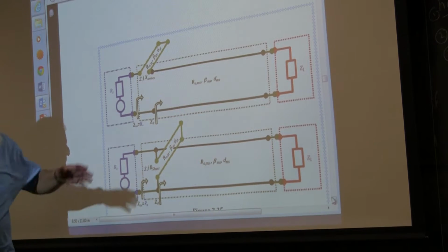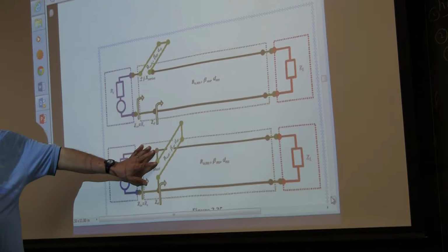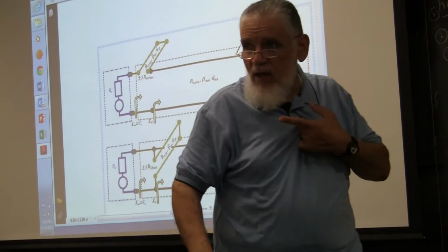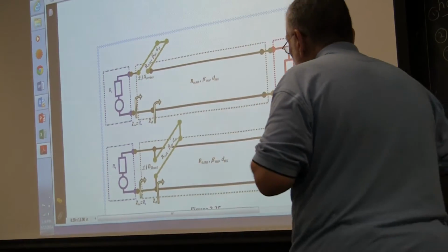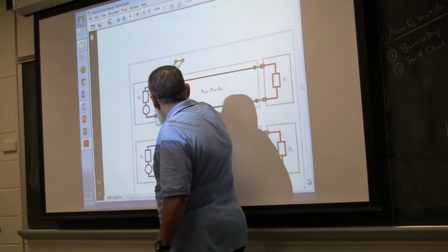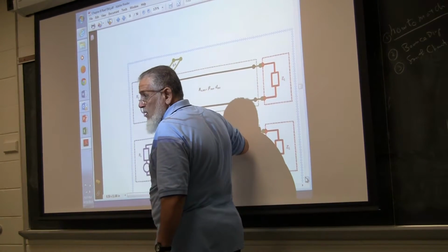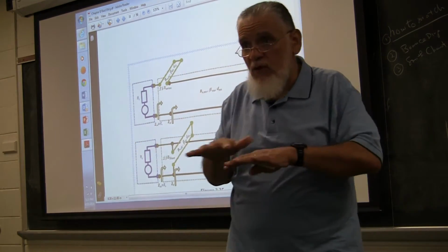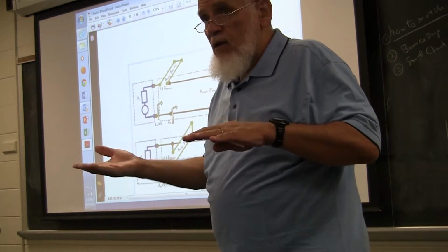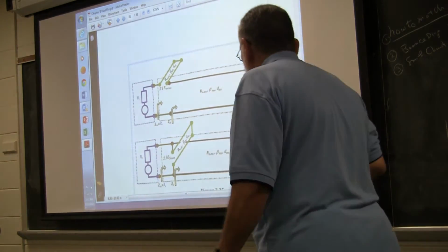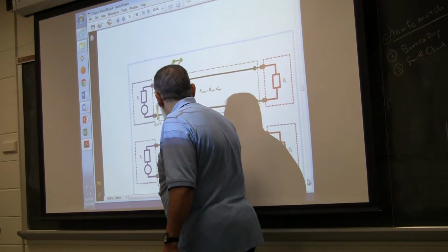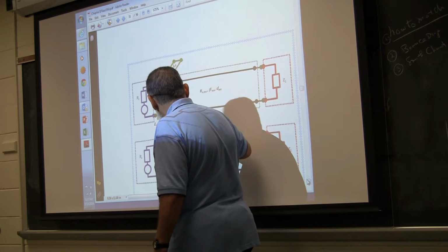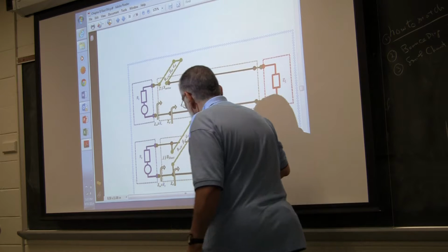These are two options. Which one do we like more? Obviously, the shunt one is better than the series one. We discussed that at high frequencies, you always would like to have a ground in your circuit. We don't like floating components. This one here is a floating component, it doesn't have a ground. This one here has a ground, right? Especially if you're building that in a certain planar geometry, for example, and you have the ground plane as your substrate. So obviously, to build that is going to be a different layer of construction. Well, this one here is easy because it contains the same ground plane as your substrate.